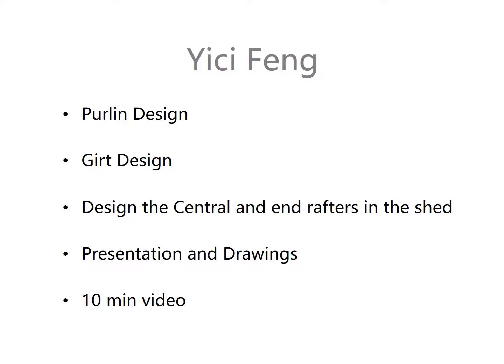After we calculate the combination of actions, we need to choose the rafter in the capacity tables and choose one universal beam. Finally, there is a serviceability limit state in the rafter design. In this part, we need to check whether the chosen universal beam is suitable for this rafter design.